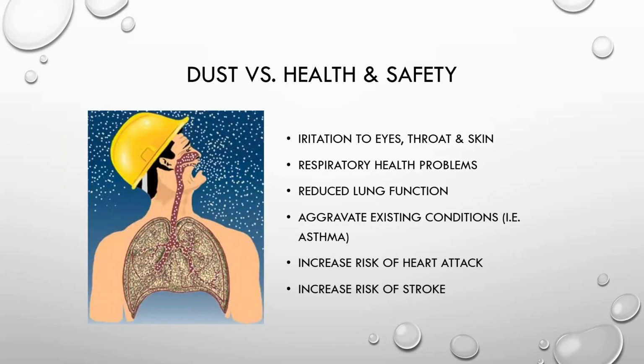While dust is often considered to be more of an environmental issue, it is also very much a health and safety risk. Usually, the nature of the dust determines how badly it can affect an individual. For example, larger particles of dust can be an irritant to the eyes, throat and skin, while smaller dust particles, less than 5 microns, can be inhaled, deposited in the lungs and cause respiratory health problems.